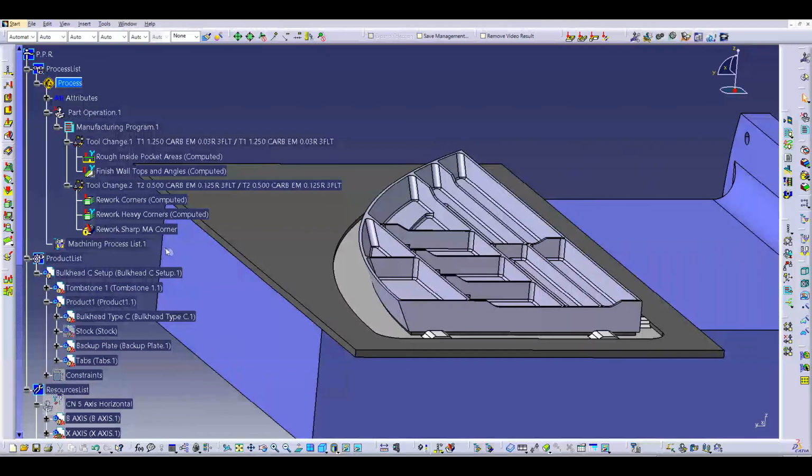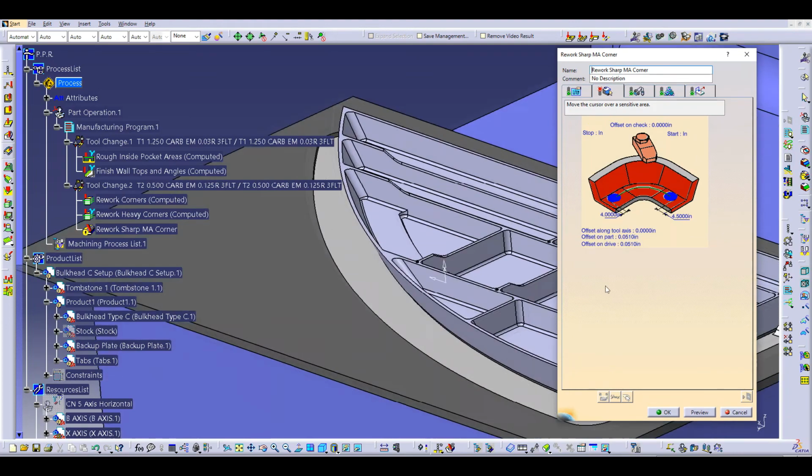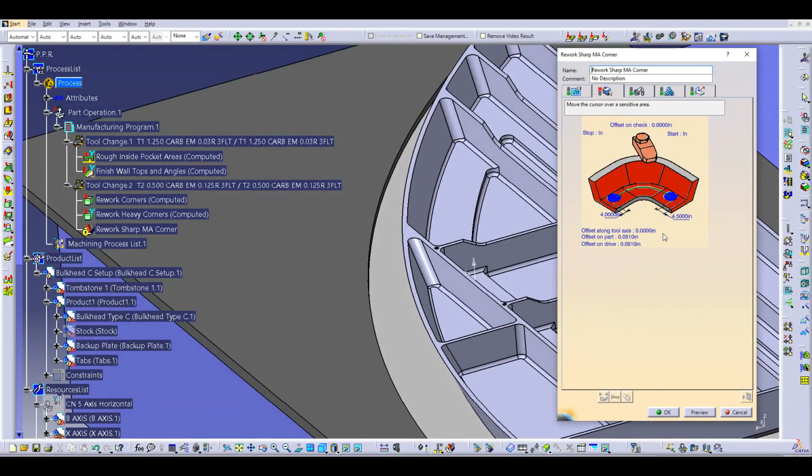Now this is what's called a multi-axis flank contouring operation. I'm going to open that up. And we're going to do fixed axis on this, but we're still using a multi-axis because it happens to lend itself better for this particular application. So what I need to do, you notice how, again, you got the red images. I can have it start in, on, or out, or tangent drive surface, and you can see how the symbol changes for you. We want it in.